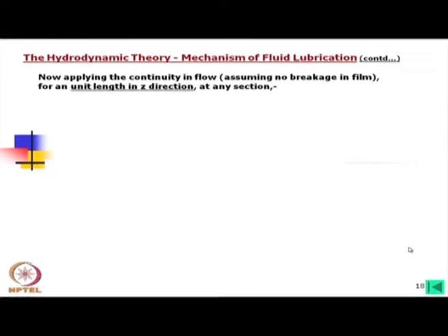Drag means one plate, the moving plate, is dragging the fluid over the other. Now, applying the continuity in flow, assuming no breakage in film. Here it is important: this theory cannot be applicable where the oil film is breaking. Now, how can we understand whether this oil film is breaking or not?